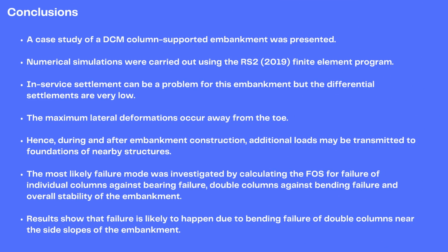Finally, the conclusions. In this case, the numerical simulations were carried out using the RS2 software for this case study, and the in-service settlements can be a problem for this embankment, but the differential settlements are very low. The maximum lateral deformations occur away from the toe.